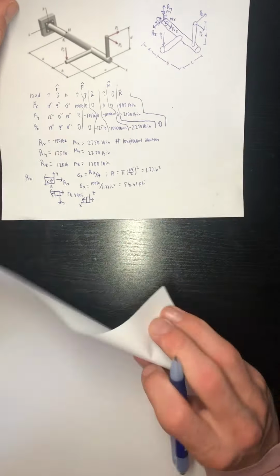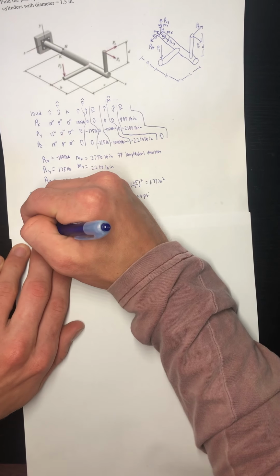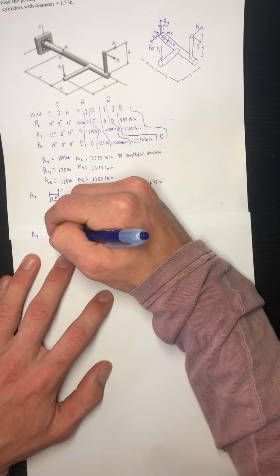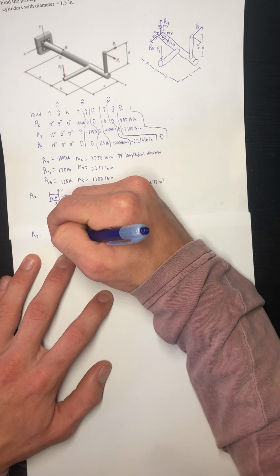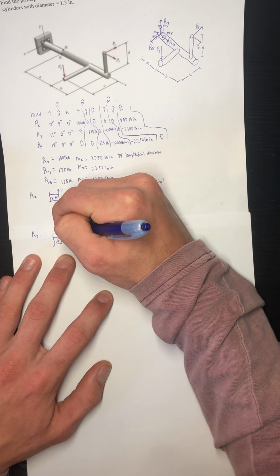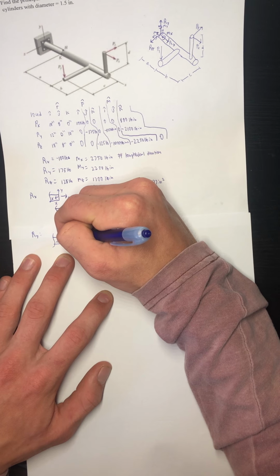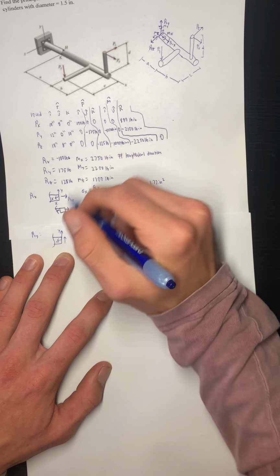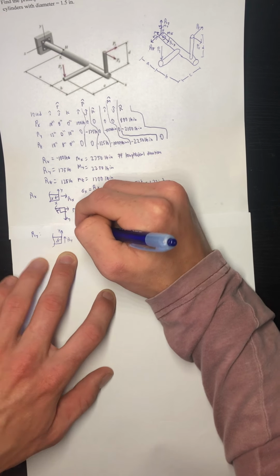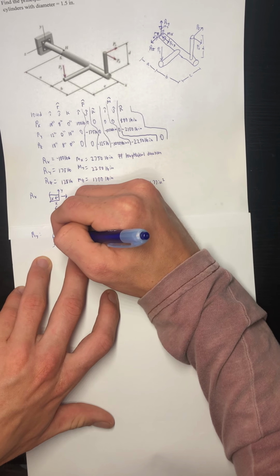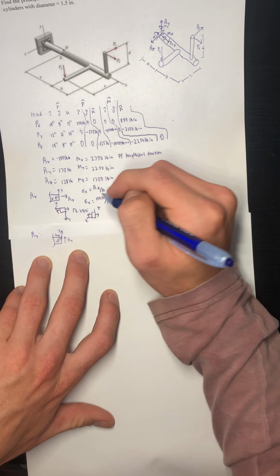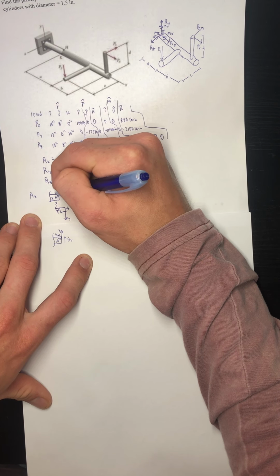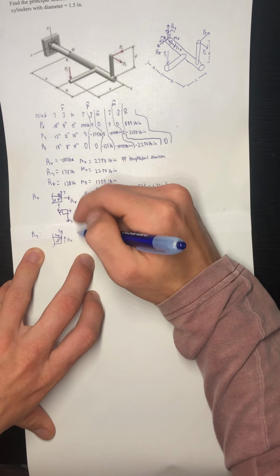Let me see here. Our reaction in the Y direction, we are again going to go ahead and pick an angle so we can go ahead and see what's going on. We have X going in and Y going up, and our reaction in the Y will be along the face of it going positive because our reaction in Y is positive, and that will be Ry. So this is creating transverse shear. By the way, our little section H is located there, and on this one it was also located on top. Section H.